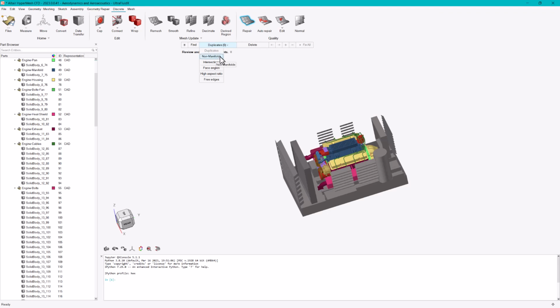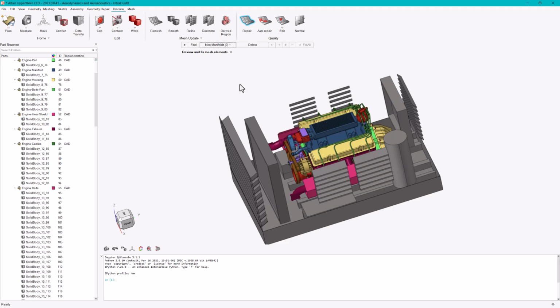User can change the search option to non-manifold. In this case, also shows as 0, and then also check free edges, as I mentioned. These 3 are the critical criteria for uFX simulation. If everything looks good, then right-click and click the check mark to finish the mesh quality check.